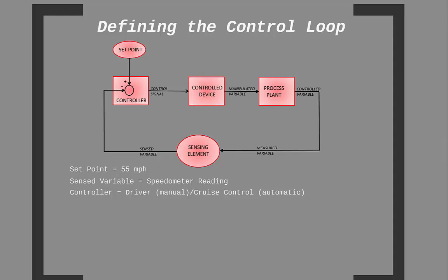In the car example, the control device would be the throttle. The control device typically is something that moves and thus requires some force. In manual control, that force could come from the human, as it did in the car example. Such a force was applied to the throttle by your sculpted leg muscle. In automatic control, it needs to come from somewhere else. The ways in which we provide that power will be explained in later lessons of this fundamentals module.